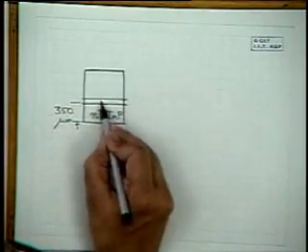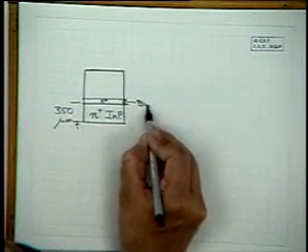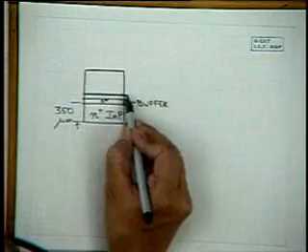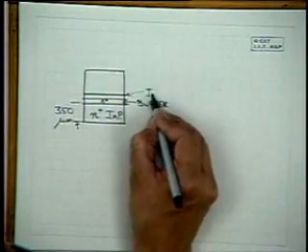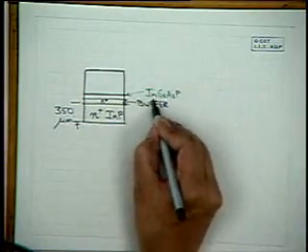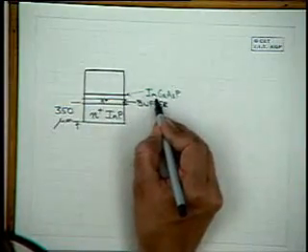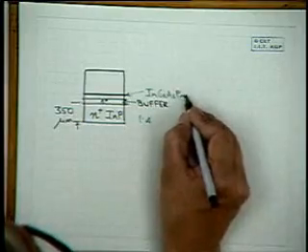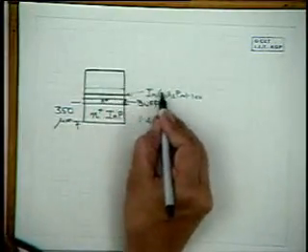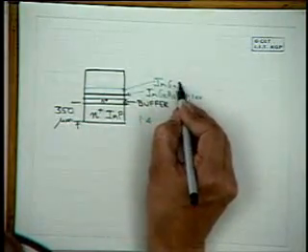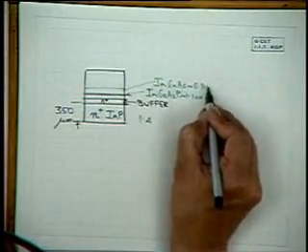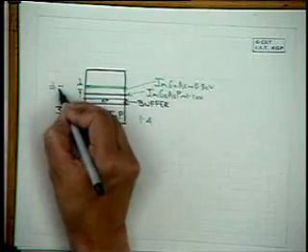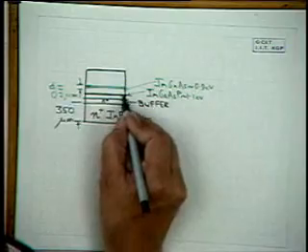then what do we grow? By MOCVD, we grow first a buffer layer of the same material, indium phosphide. Then we grow indium gallium arsenide phosphide, In(1-x)Ga(x)As(y)P(1-y), with probably a low value. Indium phosphide has a band gap of about 1.4. We grow a material with a band gap of, say, about 1.1 eV. Then we grow another layer with a slightly different value of indium gallium arsenide phosphide, with a band gap of, say, 0.9 eV. Then we grow the active layer, typically, say a double heterostructure, d of 0.2 microns. All this is N.